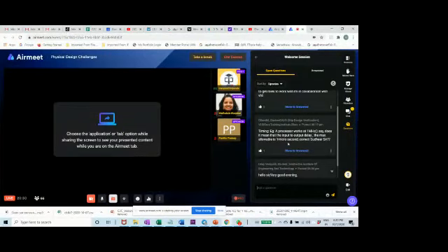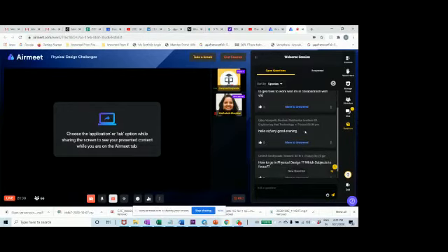Yeah, processor works at 1 megahertz, says the input to output delay max available. The question from Sri Senthil: the processor works at 1 megahertz, does it mean that the input to output delay, the max available, is 1 microsecond? No, that's not correct. When he says 1 megahertz, that particular clock period is 1 microsecond. That's the time the logic can operate between one flip flop to the next flip flop. It's not input to output of the chip. It's between one flip flop to the next flip flop. From the clock to Q delay of the flip flop to the setup time of the next flip flop, the amount of logic it can take is constrained by the clock period.